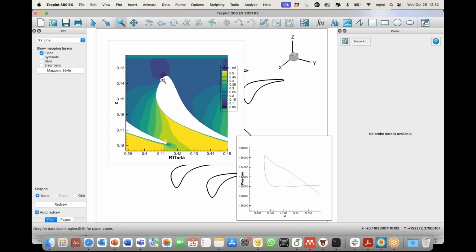Or what you could do, rather than already going for an optimization, is run an adjoint calculation and have a look at the gradient or the surface sensitivity predicted by the adjoint, so that you can spot immediately which regions of the blade are affecting your entropy generation the most, for instance. In this way, you already know which are the areas in which you can have an effect.